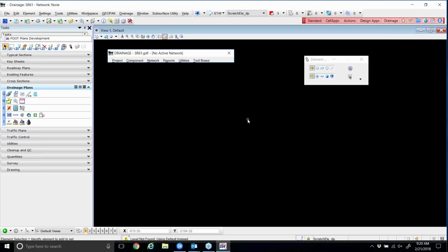This is also going to contain all of your nodes, your inlets, your junction boxes, your slotted drain. That's where a lot of the information, a lot of the work that goes in ahead of time of using GEOPAK drainage is in taking the very large design manual that we have at Florida DOT and getting all of those different nodes and all of the links as well, the pipes, into a database. That not only includes the hydraulic characteristics of those items, it includes the cells and how we want those items represented in plan, profile, and cross-section views.